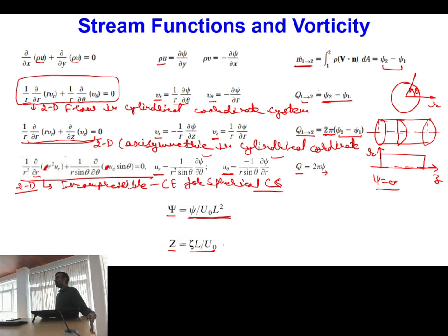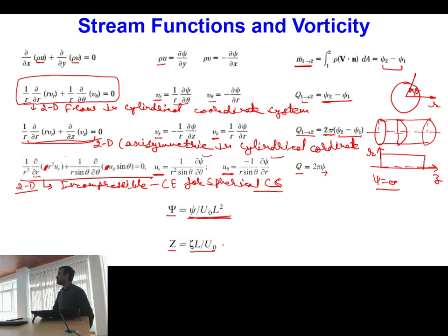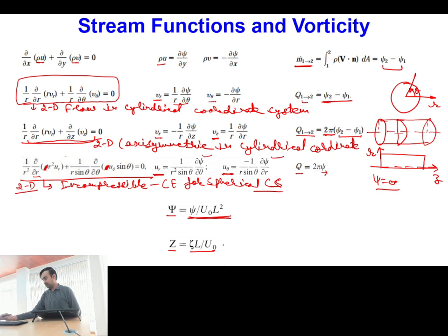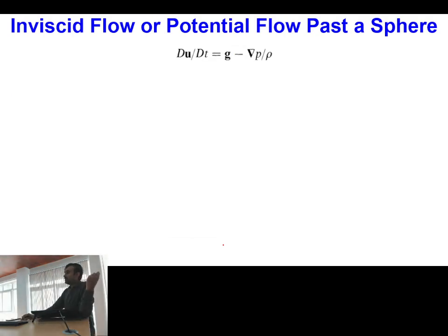Okay, so what ultimately will be happening, if you consider your momentum equation for two-dimensional flow field, then that momentum equation can be purely written in the form of psi and zeta. And once we have converted the equation in the form of psi and zeta, we can further non-dimensionalize that equation in order to write it in the form of dimensionless psi and dimensionless z. So these two formulations typically we follow for incompressible flow situations. Now let's try to see one by one different situations.